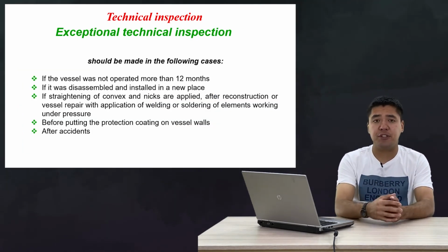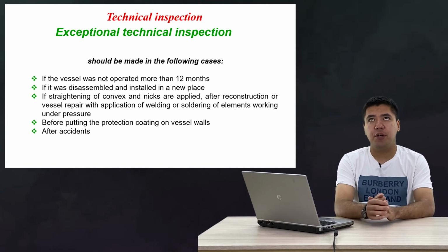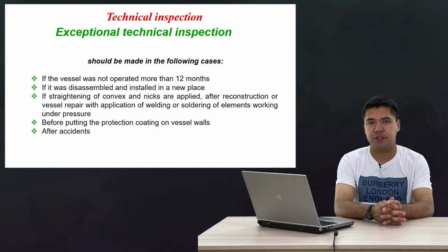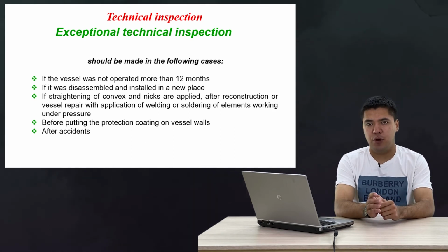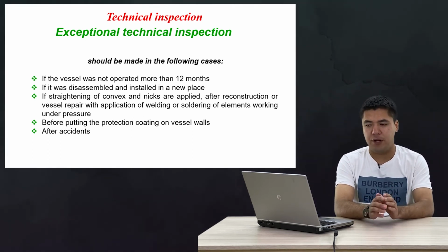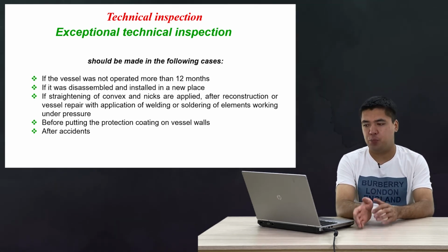And about exceptional technical inspections, when are they required and when can we do them? At first, when the vessel has not been used for more than 12 months or 1 year. The next, when it was disassembled and assembled at a new place.